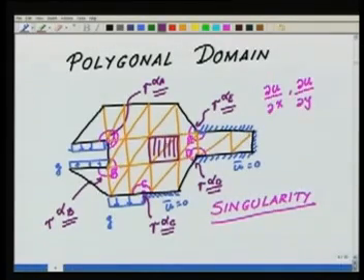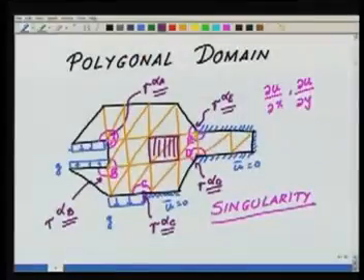For example, I may have a cutout here, I may be only interested in the vicinity of the cutout. The question is, do I have to do all this business of refinement to get an accurate solution here? In principle, from the physics, it looks like no, that really the effect of the singularities is local, and this effect dies off very fast. So away from the singularity, the solution is smooth, everything should be fine.